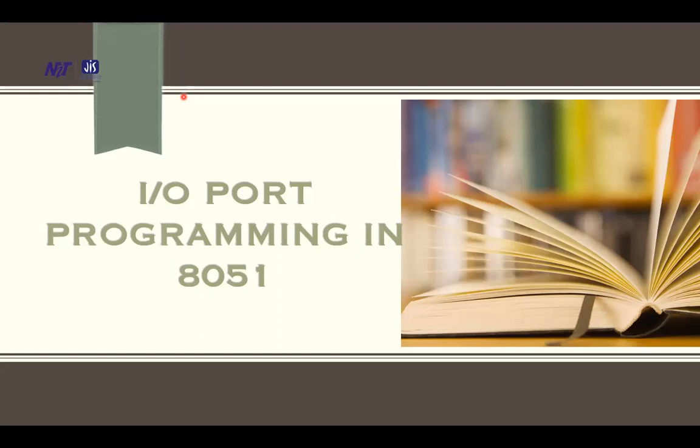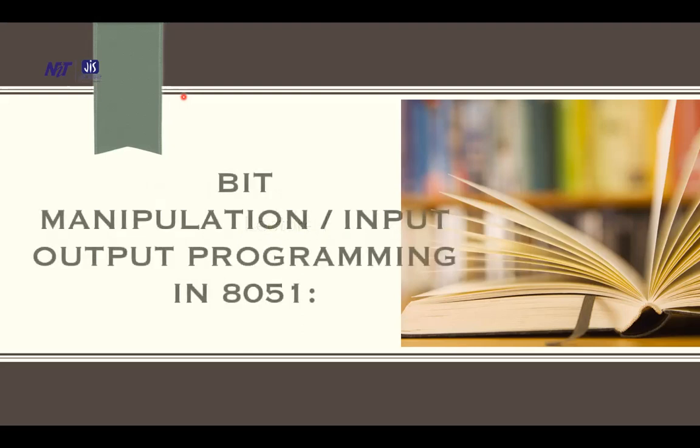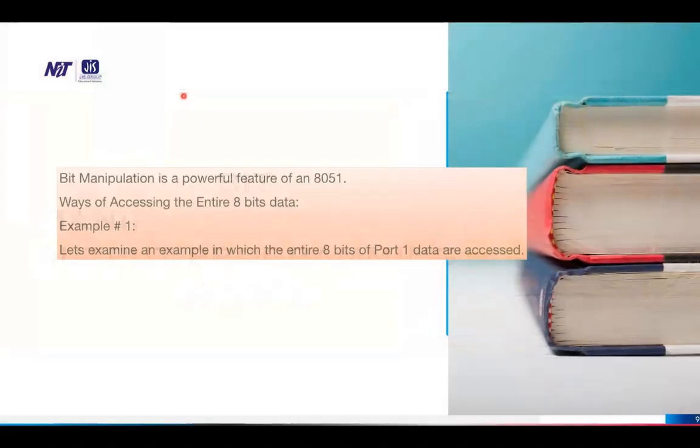I/O port programming in 8051. Lecture 5. Bit manipulation, input-output programming in 8051. Bit manipulation is a powerful feature of an 8051, with ways of accessing the entire 8-bit data. Example 1. Let's examine an example in which the entire 8 bits of port 1 data are accessed.